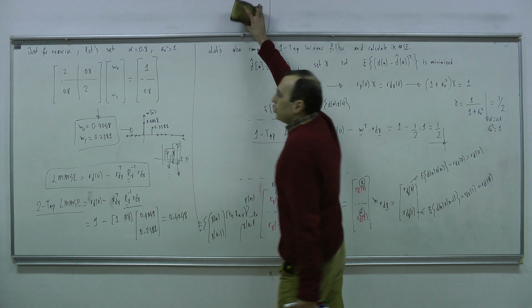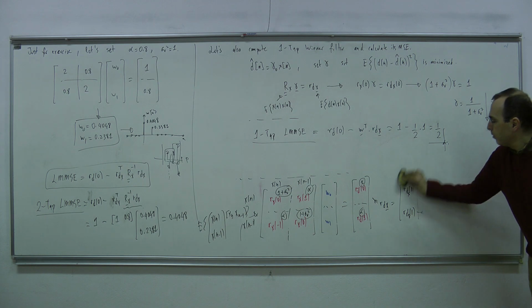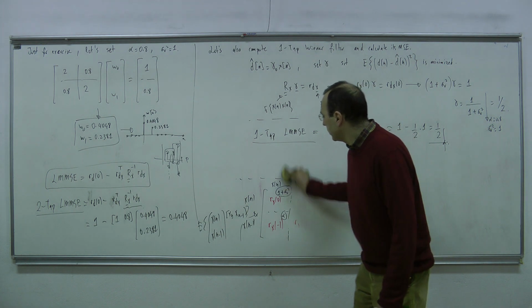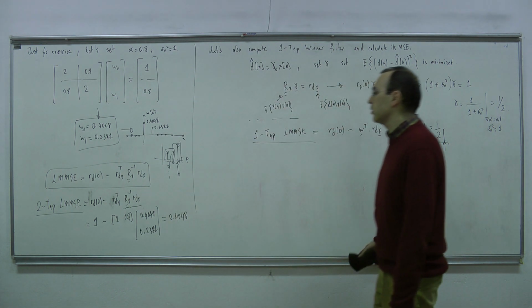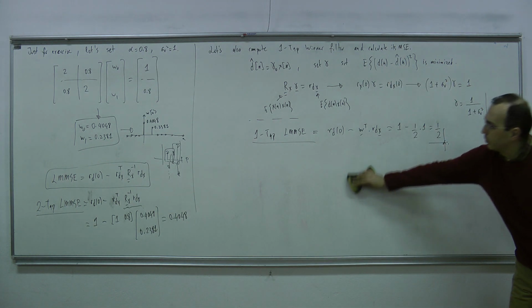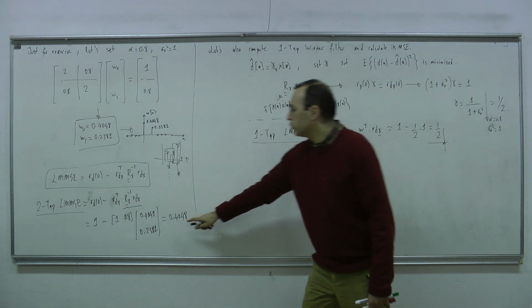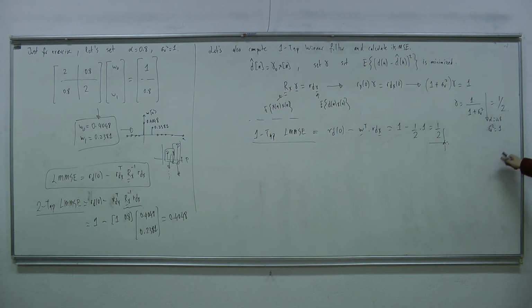Very good. So the conclusion is, maybe you are designing a system and you are trying to understand whether it is worth implementing a two-tap filter, because this is like double computation and so on. Then you can say that, of course, if this reduction of the error in terms of mean square error is important for you, then implement the two-tap filter.